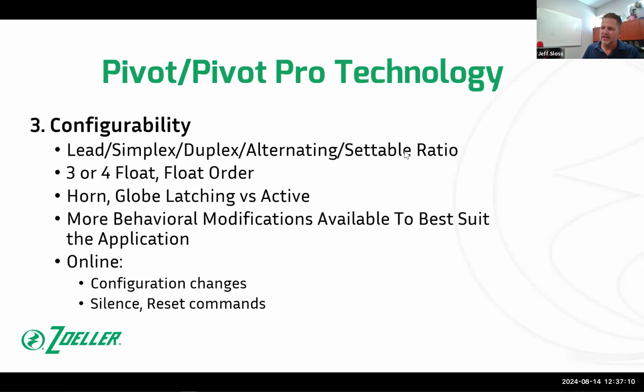So to do that, I'm going to set my station in my backyard, and I'm making this number up, 15-3. So pump A is going to run 15 times, and then the next 3 cycles will be pump B. Pump B is getting exercise, but pump B is also not being worn out. It's being worn out 5 times less frequent, or less fast, than pump A is. Hopefully that made sense. It's a settable ratio for alternating.